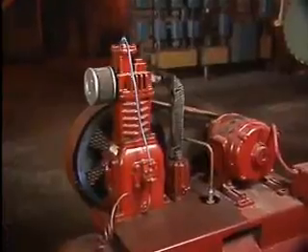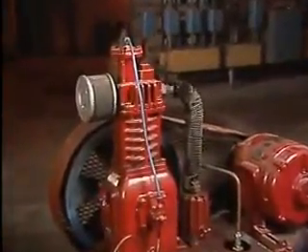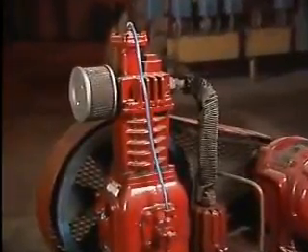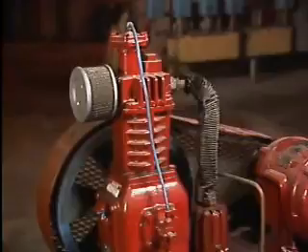In other words, more work is required to compress a given amount of gas when the gas is heated. Two techniques that can be used to remove excess heat from compressors and compressed gases are air cooling and water cooling. An air-cooled compressor is easily identified by metal fins on its casing. The fins provide increased surface area, allowing more of the surrounding air to come in contact with the casing and therefore keep the compressor cooler.